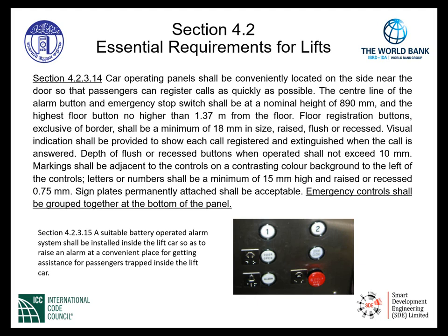Another section, Section 4.2.3.15, gives the requirement as a suitable battery-operated alarm system shall be installed inside the lift car so as to raise an alarm at a convenient place for getting assistance for passengers trapped inside the lift car. These two sections provide requirements for the car operating panels.